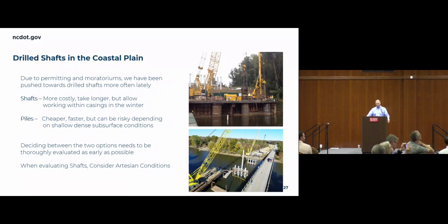And so a lot of times the permitting agencies allow us to install casings, and then we can drill throughout the year, even during that moratorium, inside those casings. And so it allows us to continue working, even though drilled shafts are generally more expensive, take longer, but sometimes it allows you to keep working. And so that's a decision that it seems like here lately, a lot of the projects have gone from what would have normally been a pile project to a drilled shaft project because for that specific reason. But again, they are more costly generally.